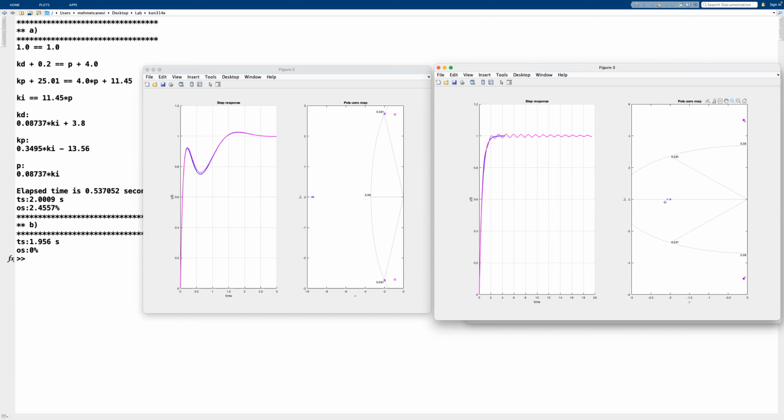Whereas if the pole zero cancellation happens more towards the left, which is not even close to each other, for example, if this is the structure, then you can see we're much safer in terms of modeling errors, because at least they are going to be stable modes. It will mess up the whole shape of the system response, but we would be happy with that instead of having something that is not stable. Well, let's go back to our original discussion.